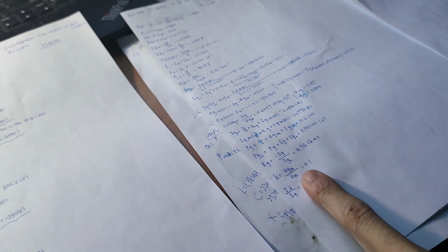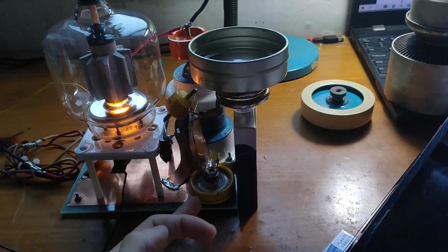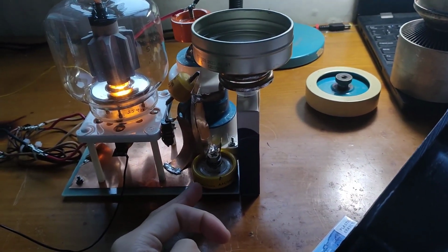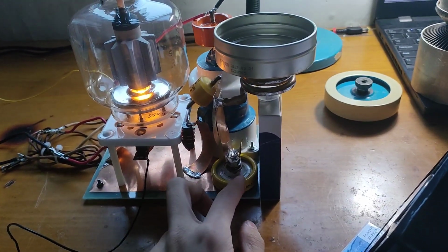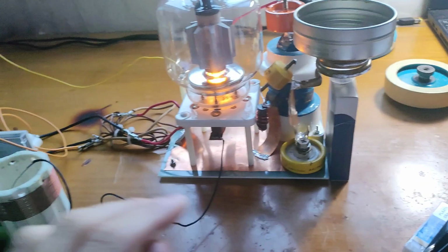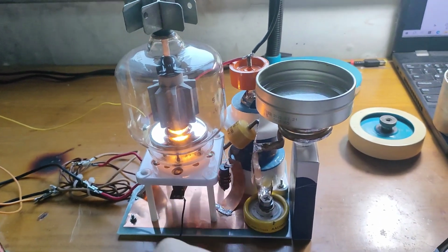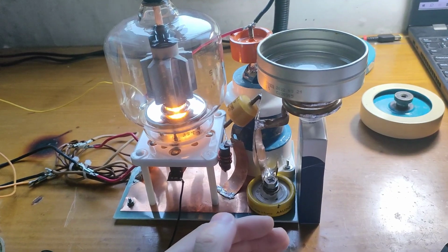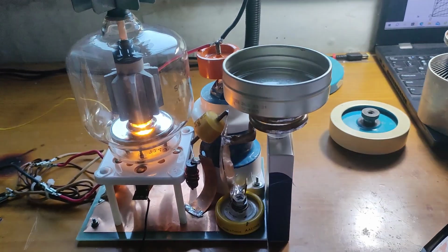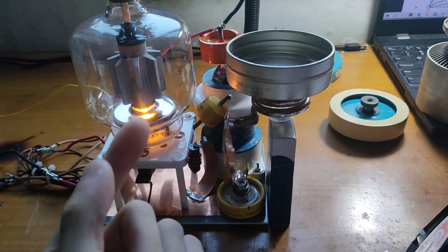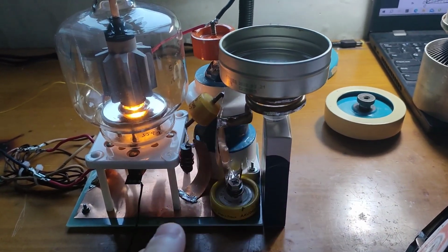So to sustain a stable oscillation, you need a feedback ratio a bit larger, usually 2 to 2.5 times the designed feedback ratio. So I just simply use 2 times the designed feedback ratio, but that will lead to a larger grid feedback current, and that also means that the oscillator is dangerous to operate under no load condition at full power, because you will risk your grid, right? The grid dissipation will be higher than your design, many times higher, around 4 times higher in this situation.